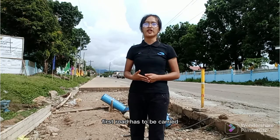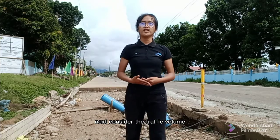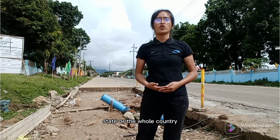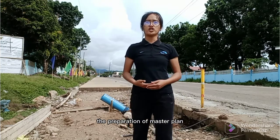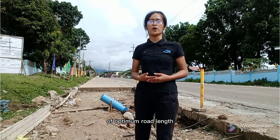First, roads have to be planned according to the different season and weather conditions. Next, consider the traffic volume, road transport, location, function, etc. The road length required for an area, it may be a district, state, or the whole country. The preparation of a master plan showing the phasing of the plan in a 5 year plan or annual plan. And the next plan will be prepared by considering the economic studies, financial studies, traffic and road use studies, and engineering studies. And the last one, it also includes the determination of optimum road length.